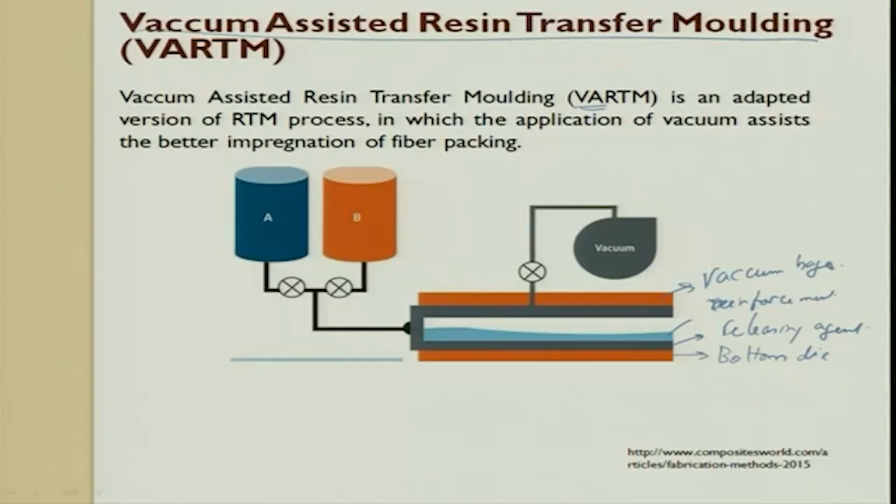This is what is called vacuum assisted resin transfer molding. Today these processes are coming up in a big way. Wherever you want a higher volume fraction, that means 70% to 90%, on a flat plate reinforcement, this vacuum assisted resin transfer molding process is exhaustively used, even for small plate making. For research purposes, people always used to make the composite out of hand layup. I would suggest you should now look for vacuum assisted, so that you get a sound product for your output.